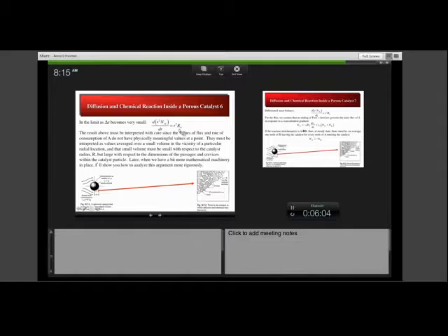Now, we've also assumed that this is operating at steady state, and in general, this is a reasonable assumption because the time scale for these tiny catalyst particles, which would often be on the order of millimeters to a centimeter or so, the time scale for them to come to steady state is often orders of magnitude smaller than the time scale for the entire device to come to steady state.